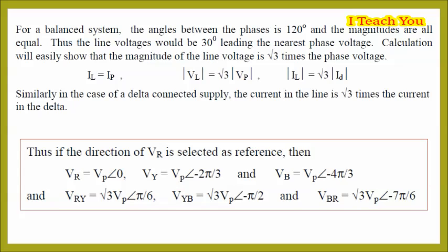and for this purpose, the line voltages must be specified in a sequential manner, for example VRY, VYB and VBR. Note VBY is 180 degrees out of phase with VYB, so that the corresponding angles, if this is chosen, may appear to be 60 rather than 120.